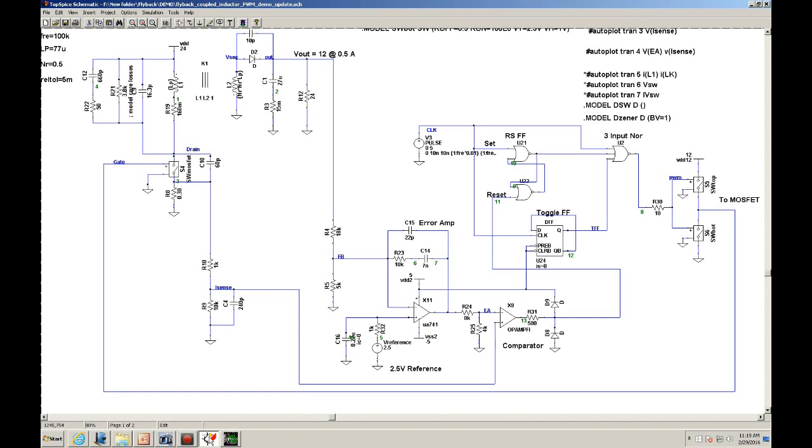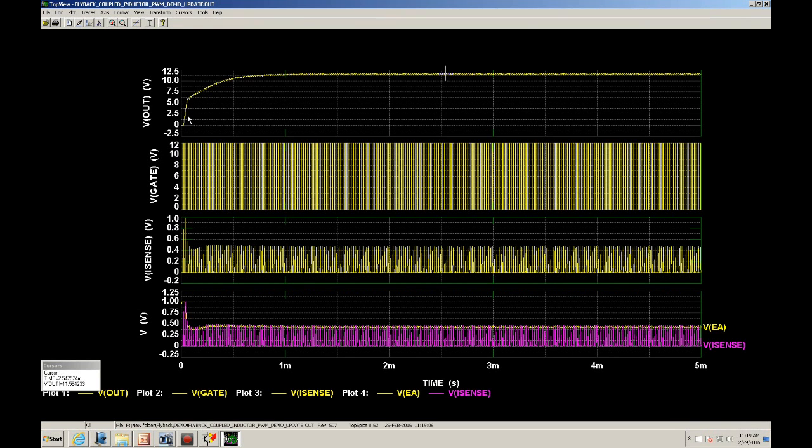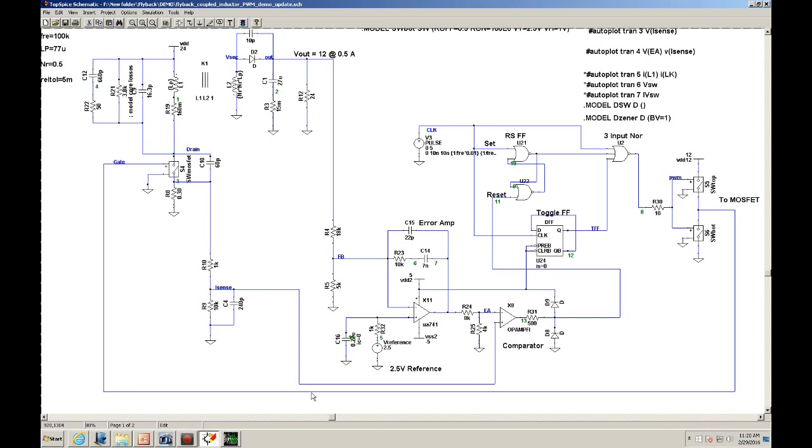So what you can do is you can raise, well, actually make this a little bit higher, and yeah, you raise R4 and that will raise this voltage. Okay, and if you notice, it comes out really nice, very controlled exponentially. Okay, and the reason that does that is because of this cap and this resistor.